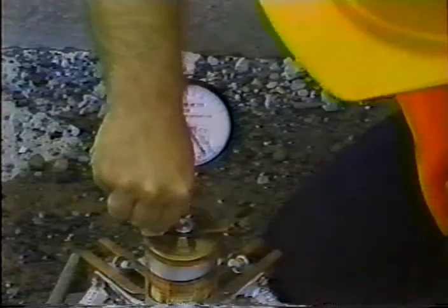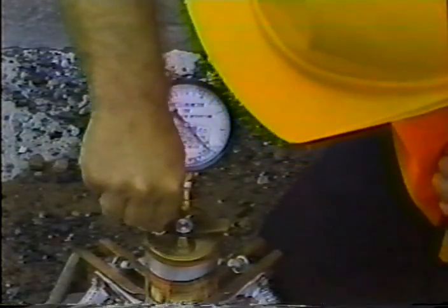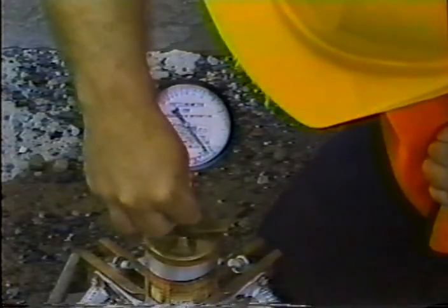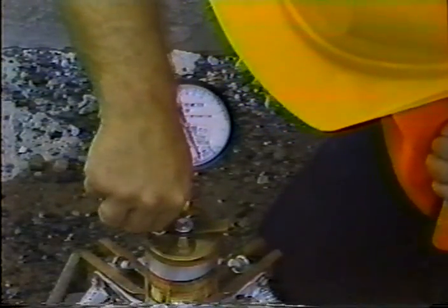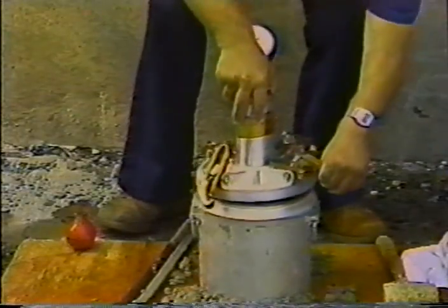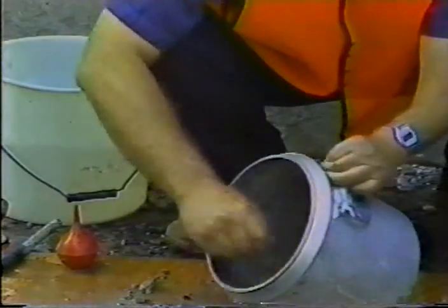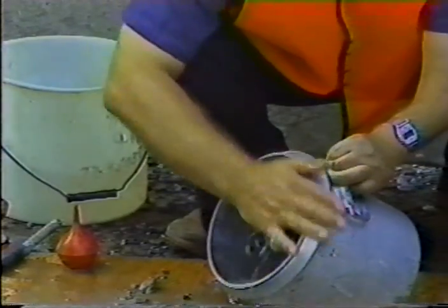But just a few more points before I finish. No test is valid unless it's performed correctly, in the same way each time, using properly calibrated equipment in good condition. Use the equipment carefully without damaging it. Keep it clean. Air content should be recorded on the delivery slips. Be neat, complete, and accurate in your documentation.